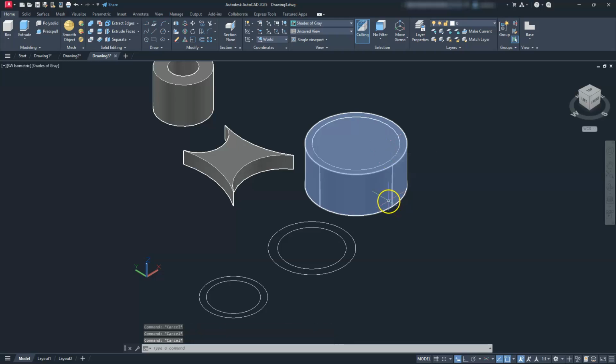Now, I really didn't have to keep this center circle on the inside of this one because they're going to be joined together, but I like to do it that way just so I can keep everything together, if that makes any sense, right? Okay, so I'm going to knock out that step. And what this is basically representing, and now that I think about it, this inside line, actually, I can extrude it down a height of 5 just to get rid of that cutaway through it.